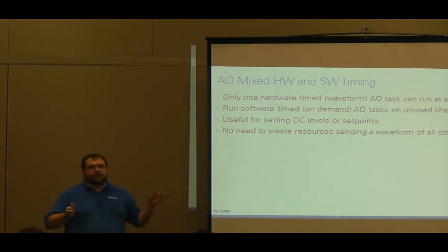Whereas if I have a waveform that I output of 5 volts, and I change my next buffer write to 3 volts, I have to generate out the entire buffer that's existing before I get to my update. So in many cases, this will actually update more quickly and more responsively than if you did all of your channels hardware timed.